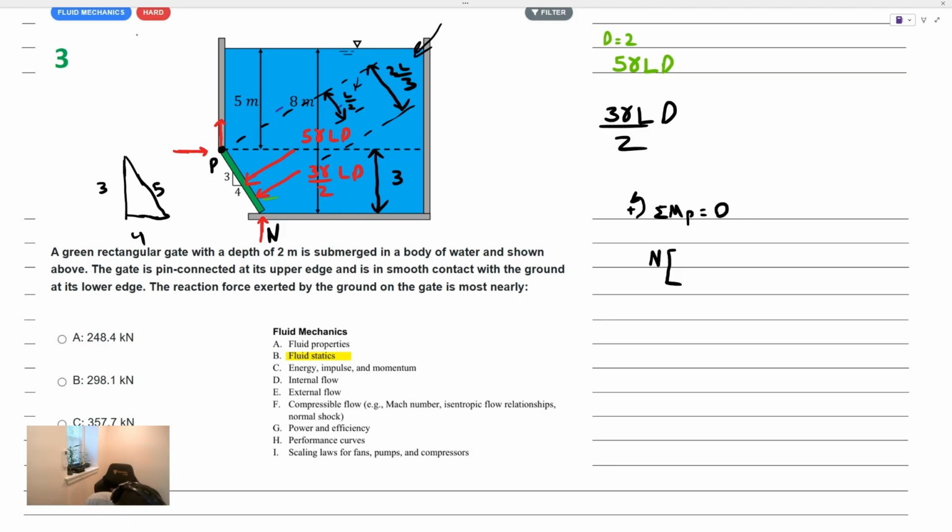Instead of writing in terms of numbers, I'm going to say it is L, and I'm going to call this theta here. We know that the horizontal distance would be L cosine theta, and the cosine of theta is just 4/5. So I'm going to call that distance 4/5 of the length. And that counterclockwise contribution must be equal to the contribution here due to all the clockwise moments.